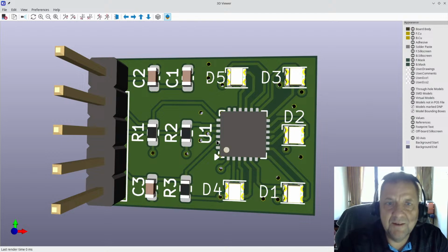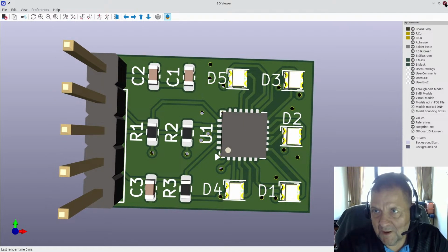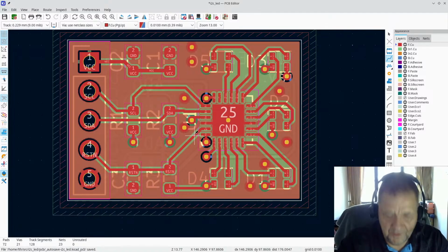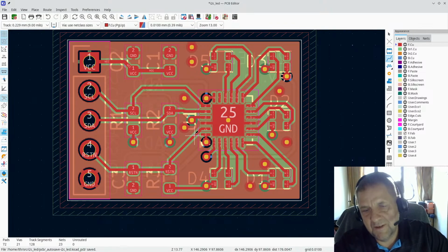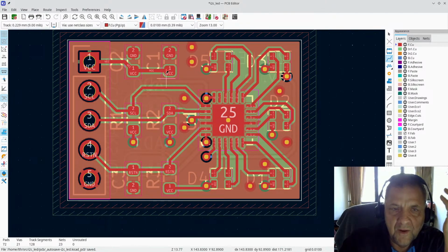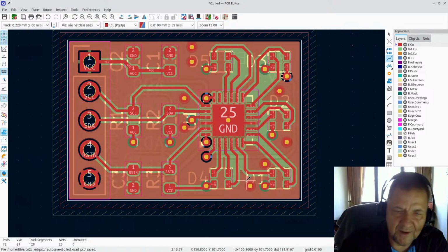And these are the things, like, now, if this had been a production board, I would probably do this thing. One of my arguments that I always say, don't be afraid of ripping traces up and reroute it. As you can see, once you got the components placed and you're happy with the layout, the routing is the quickest part at all.